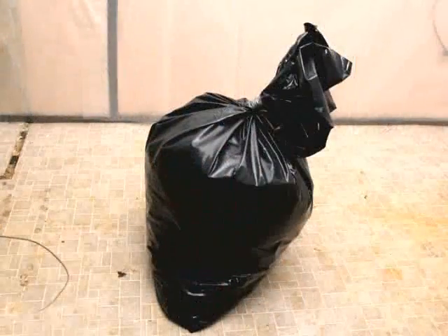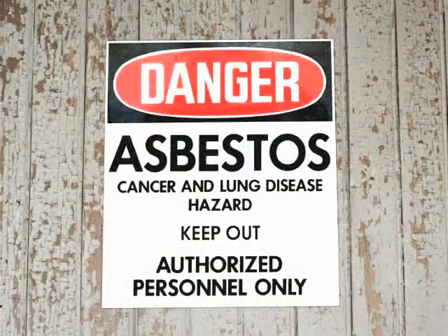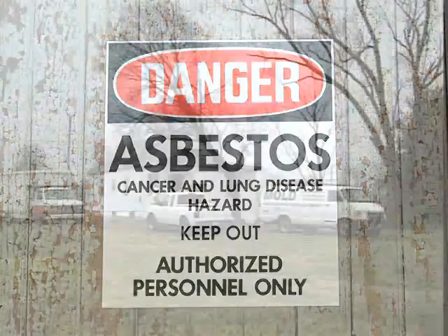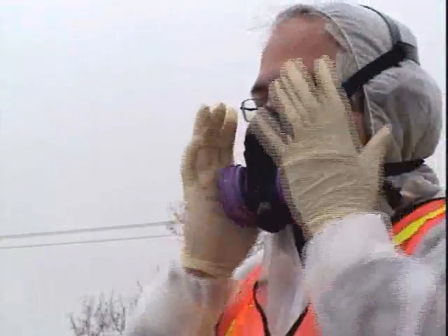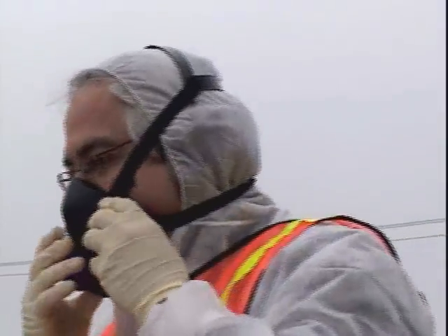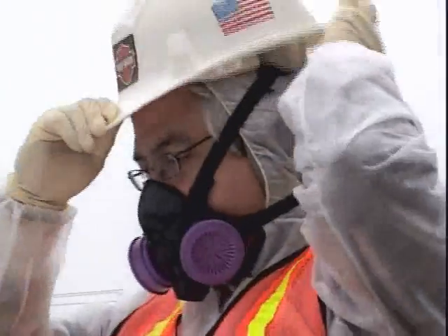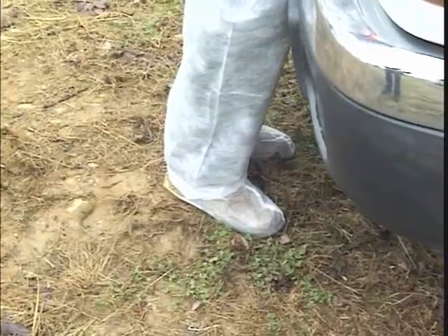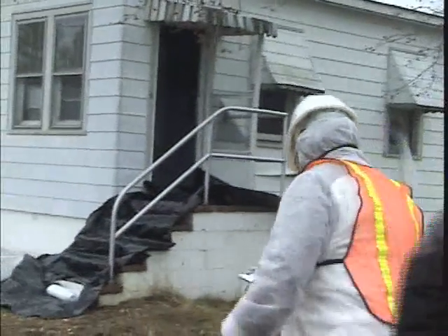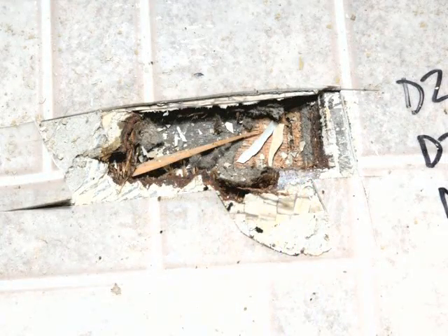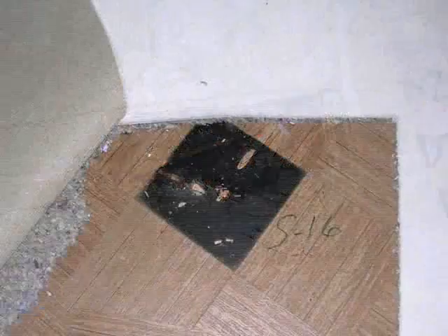Inspection, removal, and disposal of asbestos is regulated by several federal and state agencies. Localities and sponsors should be aware that any structures to be rehabilitated or demolished must be inspected for asbestos by a licensed asbestos inspector. A licensed inspector will report any asbestos-containing material found in the structure and classify the material as friable or non-friable. Some non-friable asbestos-containing materials, such as floor tiles, do not necessarily need to be removed if it is not likely to become friable during demolition or rehabilitation.